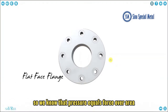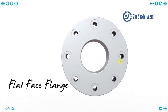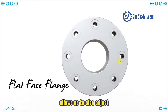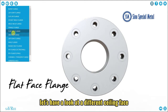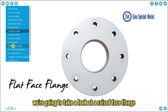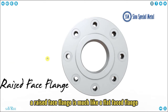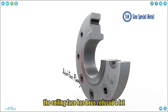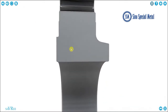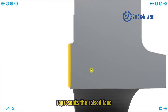So we know that pressure equals force over area, and we know that adjusting the area allows us to also adjust the sealing pressure of a flange. Let's see that in action. Let's have a look at a different sealing face. We're going to take a look at a raised face flange. A raised face flange is much like a flat face flange with one difference. The sealing face has been reduced a lot. This area, highlighted in orange, represents the raised face.